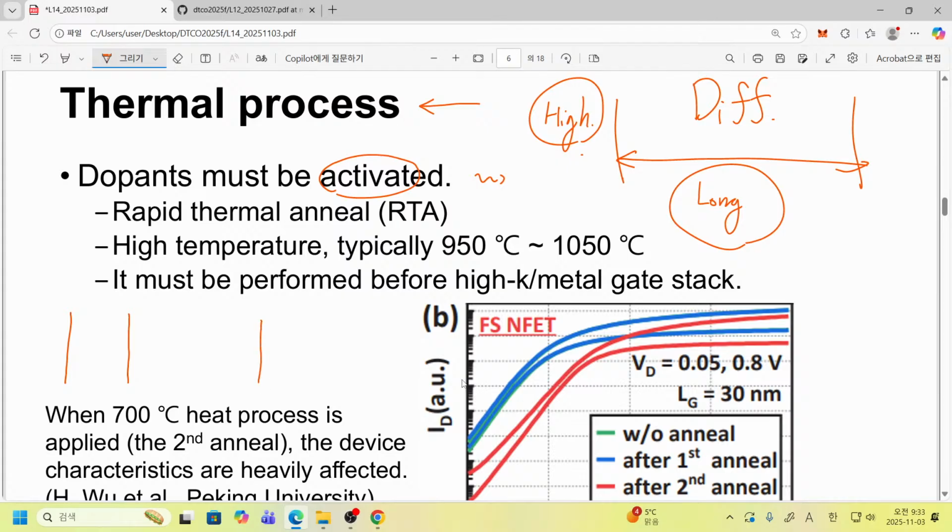Let's say that here we have a silicon, and here we have an epi layer, and also an epi layer on the other side. Usually this silicon channel is doped from its initial process, and its range is known to be about 10 to the 16 or 10 to the 17 per cubic centimeter.